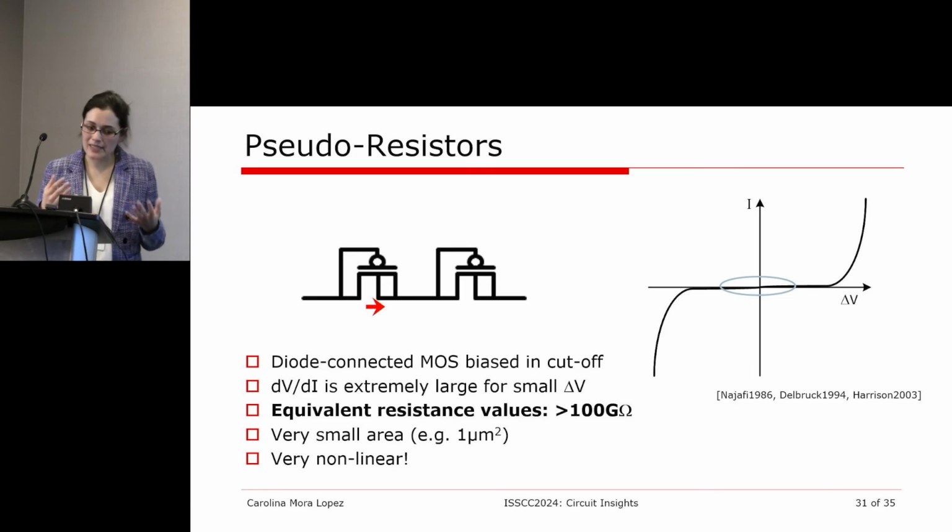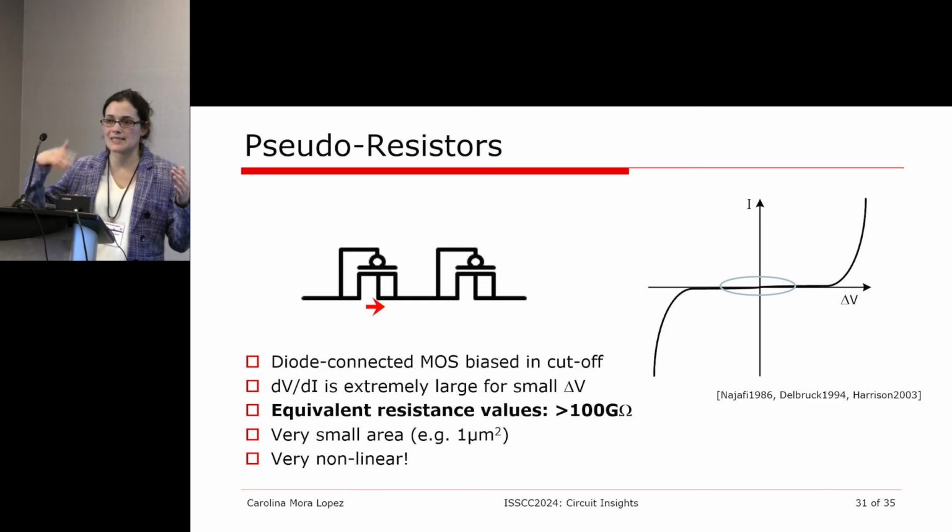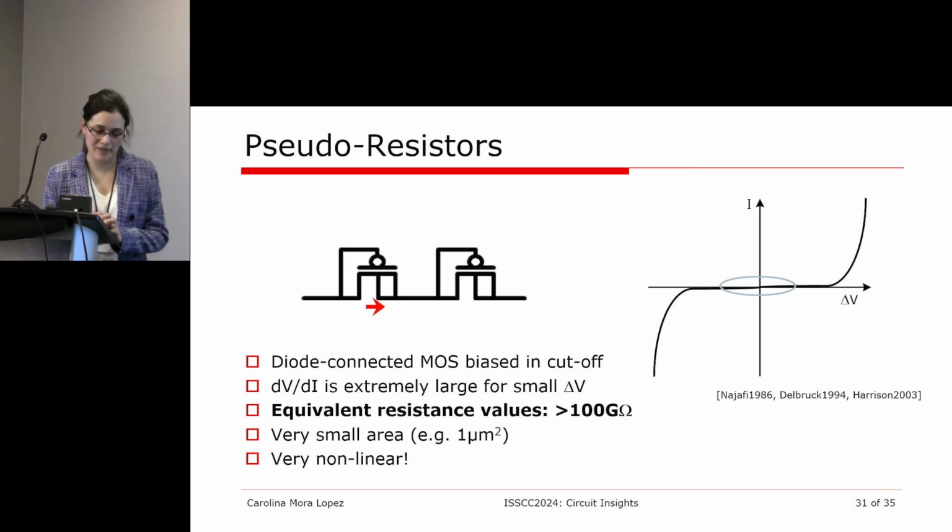So it's not ideal for applications where your resistor will see large voltage swings along the terminals. It also varies a lot with process variation and with temperature. So it's very difficult to predict the exact value of this resistor, but still, if you have enough margin in your design, for example, you design for less than 1 hertz, but you don't care how low it can go, it can be 1 millihertz, and it can go to 1 hertz, for you it's the same, then this can be acceptable, but you have this uncertainty, and that will affect also how you design this element